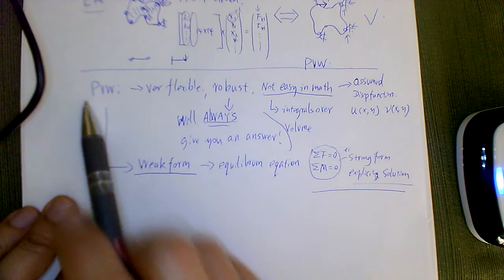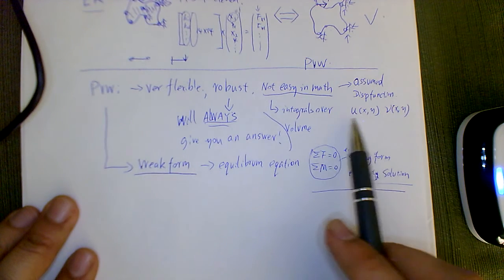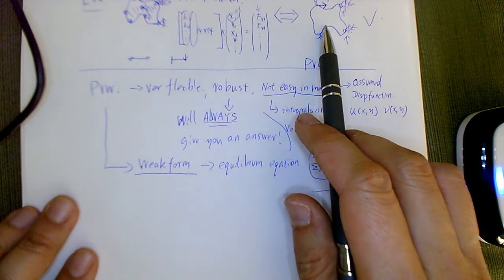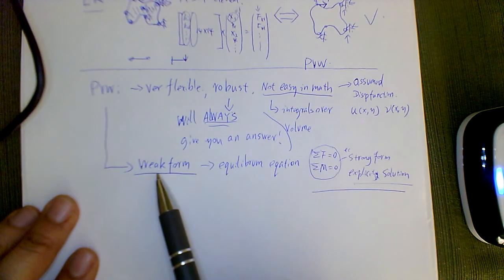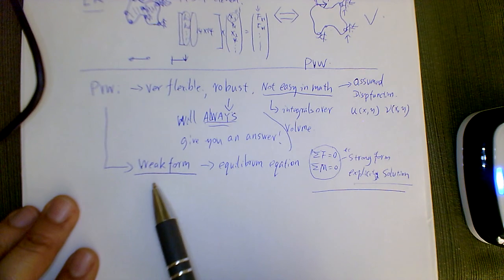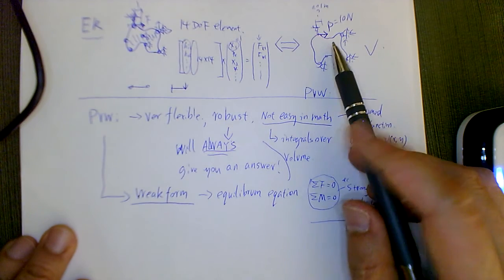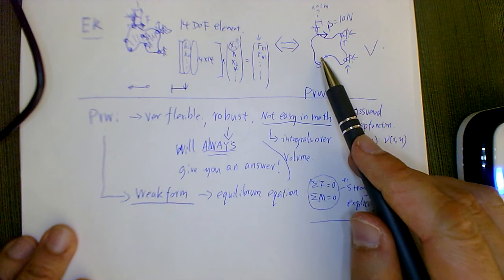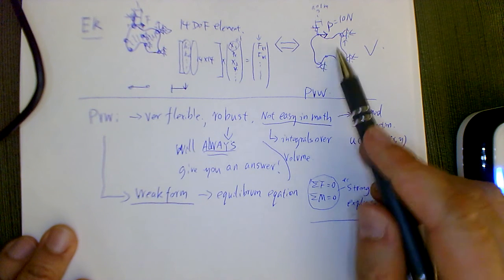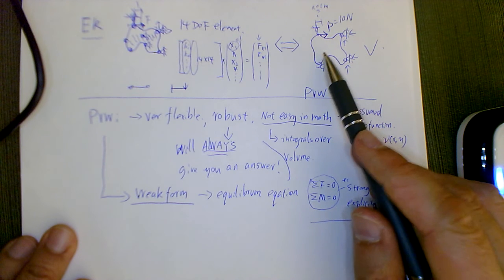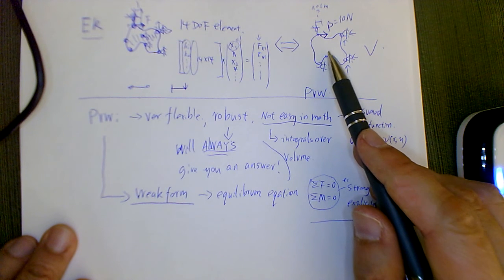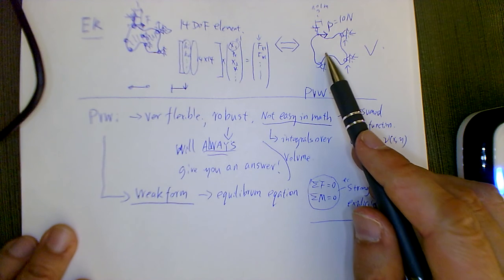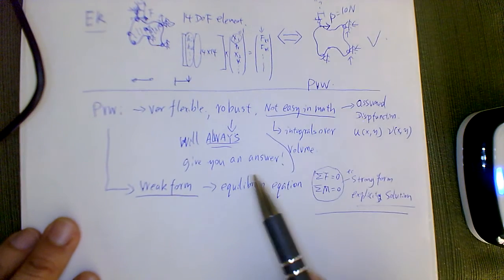But with the principle of virtual work, the weak form, you can have something where you don't have to satisfy the equilibrium at every single point. What it enforces is that the overall energy of all your stress, strain, and external force, on the energy level, the deformation, everything should be in harmony, so that virtual displacement or virtual deformation does not result in any work.